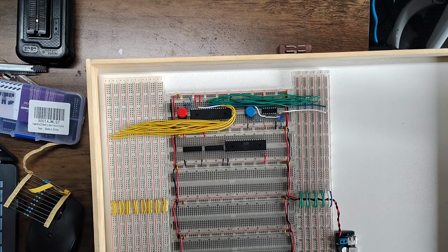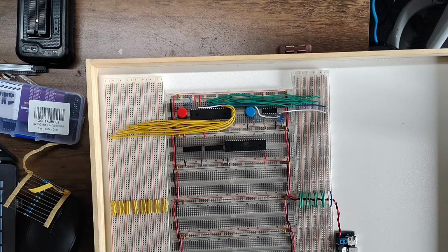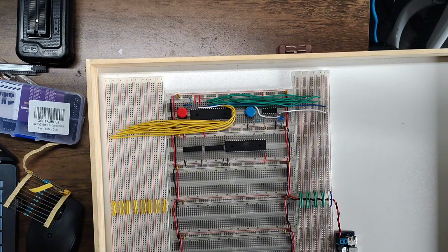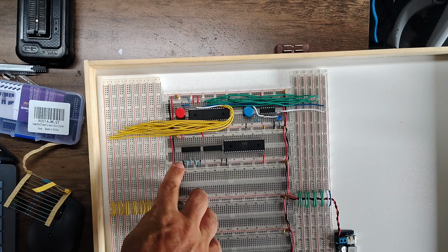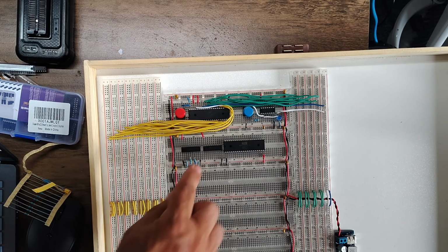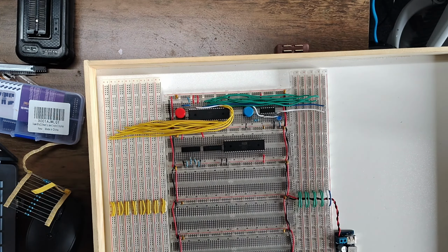Okay, now the next thing I need to do is program the first 4 bits of my address. So if you remember, we want to write to address 6000 through 600F. So the first 4 bits of that would be 0110, which would be a 6, and that's what I want it to be. And then the pins in between are what's going to come from the address bus, and that's what it's going to compare it to. So I'm just going to pause it, and I'm going to put in those 4 address wires.